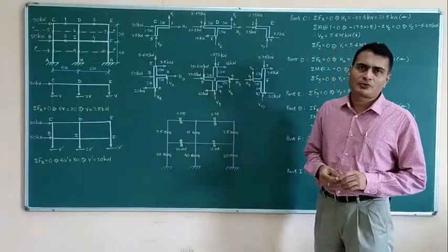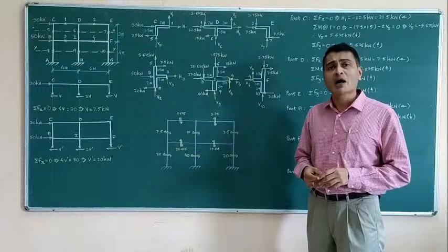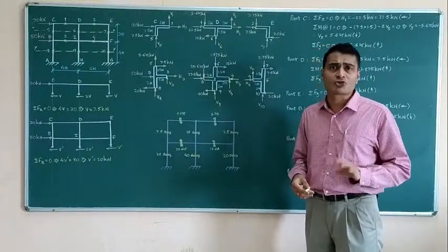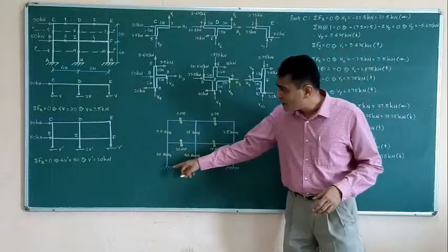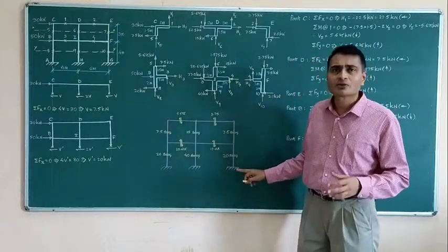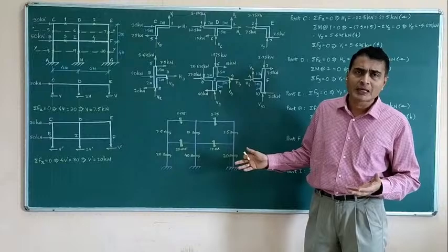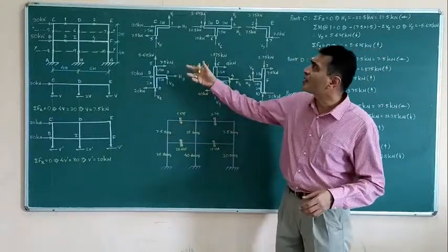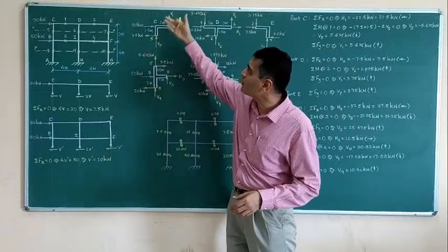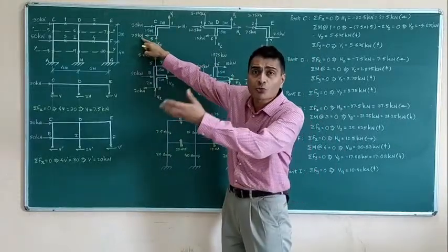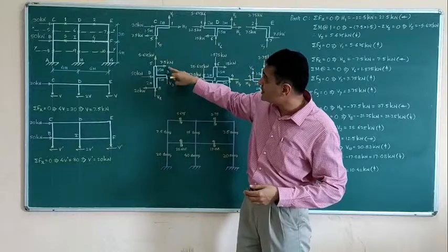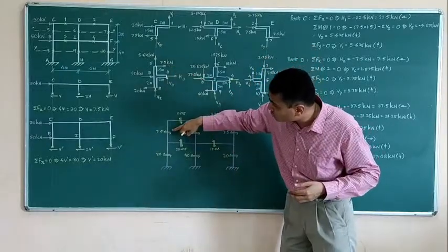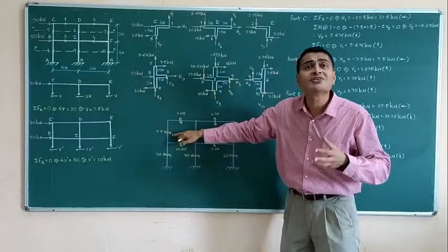To develop the moment diagram and to indicate shear forces and axial forces, what have I done? I have just redrawn the given frame, and then at each point of contraflexure, as we are aware of the shear, for example, for the upper portion it is 7.5 leftwards, for the lower portion it is 7.5 rightwards. So here I have shown leftwards above, rightwards below, 7.5.